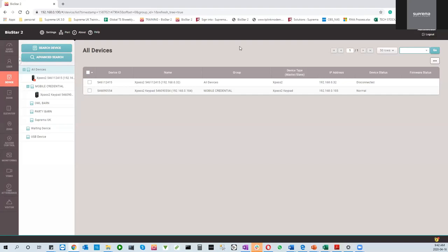So basically, let me recap. You come on site, you've already installed the CoreStation, you picked up an R2 reader, you purchased an N2 reader, and you've also purchased an XPass and an SIO. The first thing you want to do now is connect the CoreStation to your network. Your laptop or desktop PC would also be connected to the exact same network.